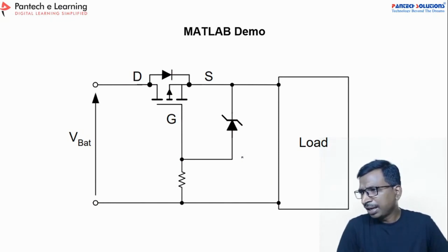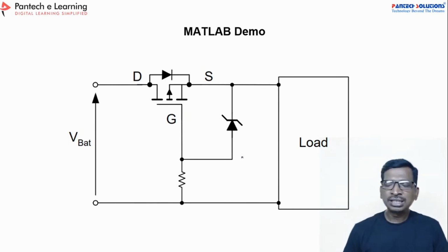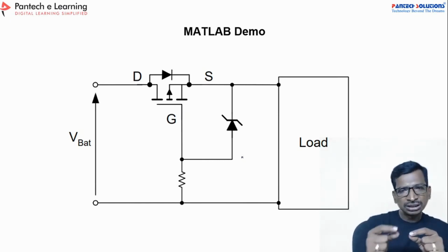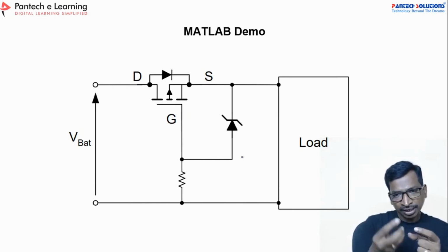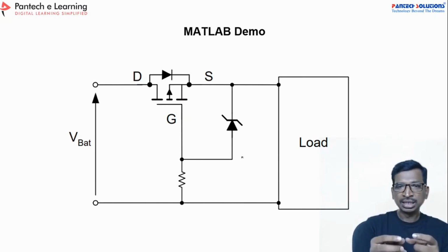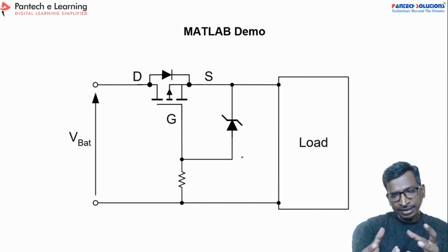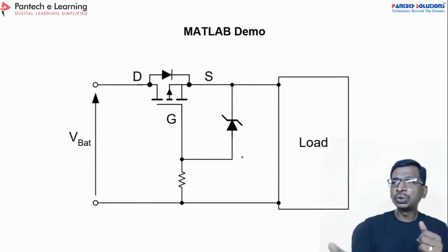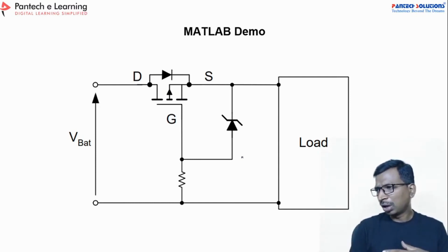What is the cause behind the battery of electric vehicle not charging after connecting the charger? There is no fault in supply. So there is a chance for the pilot wires. There is a chance for the connectors in the pilot wires. There is a chance for the battery failure. So these are all the adequate points you have to ensure to debug your system.